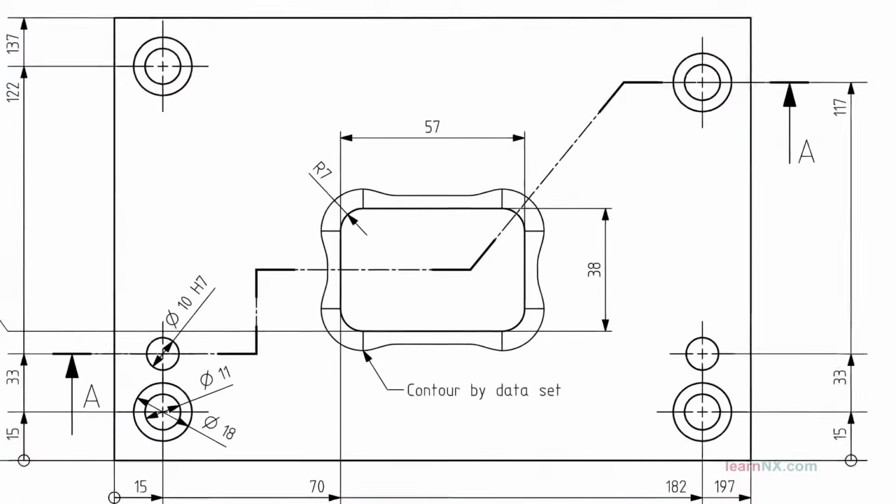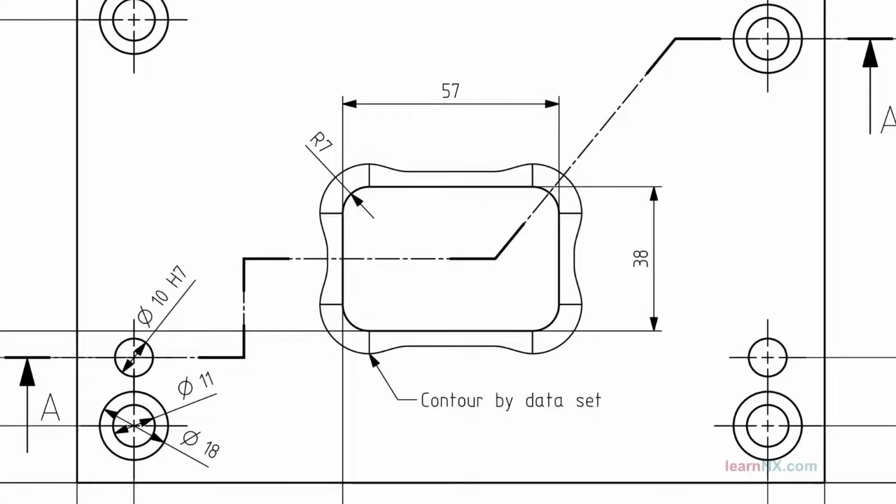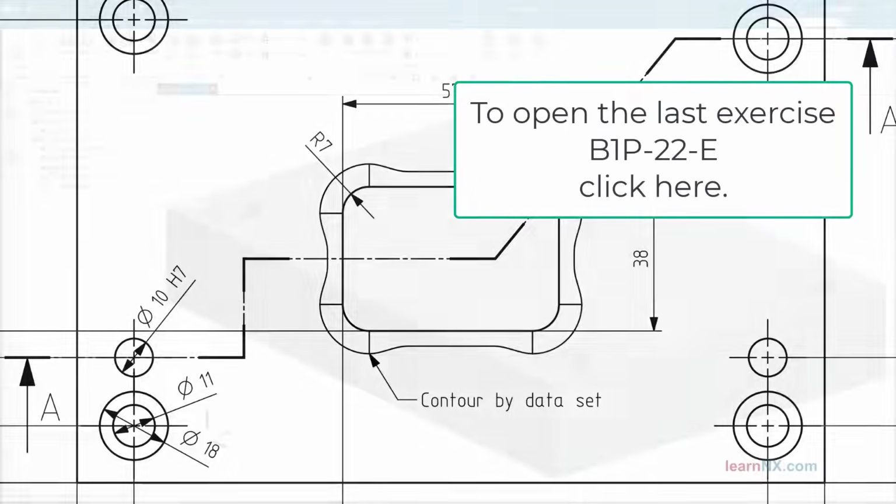Create rectangular opening. The dimensions for the rectangular opening take into account the dimensions of the drawing mandrel, with 1 mm sheet thickness.